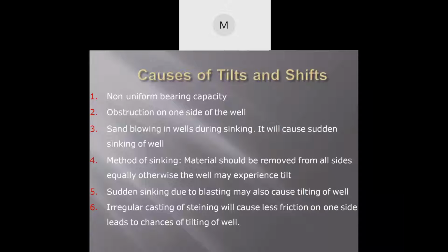Then method of sinking. The material should be removed from all sides equally. Otherwise, the well may experience tilt. You understood this thing because the debris or any other material that is present on the side of the well should be removed, or else the well may experience tilt. Now, sudden sinking due to blasting may also cause tilting of the well.